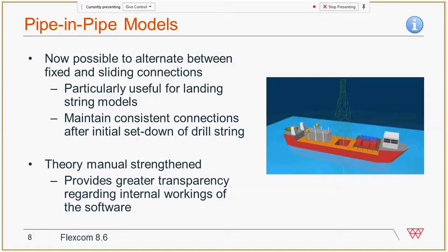The other option is sliding, which is where the relative axial motion is very significant. So in that case, let's say for a J tube pull-in, where you're pulling a flexible through a J tube, the inner tube slides inside along the outer one quite a long distance. So at every solution step, Flexcom monitors the outer nodes against a group of inner nodes, and based on the relative axial location, it picks out the right connections automatically for you.